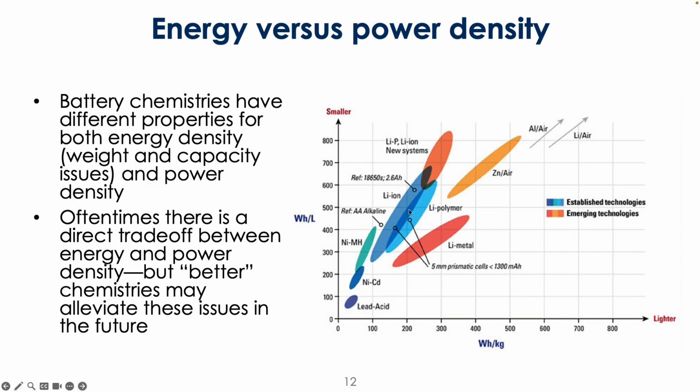The one that's used in electric vehicles is lithium-ion batteries, in comparison to some of these other chemistries. So lead acid, the big, heavy, bulky ones that are used in traditional cars today, and you'll actually find them in electric vehicles as well for somewhat antiquated reasons. Then you've got nickel metal hydride, which was in a lot of the early generation hybrids.